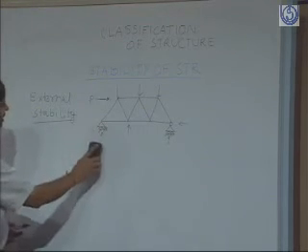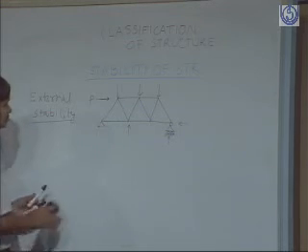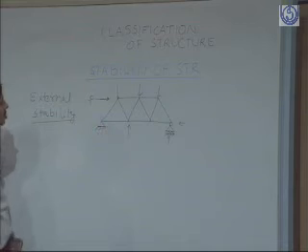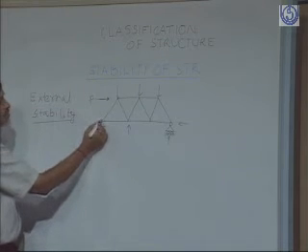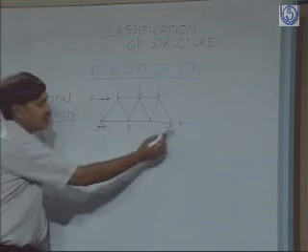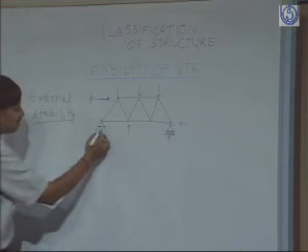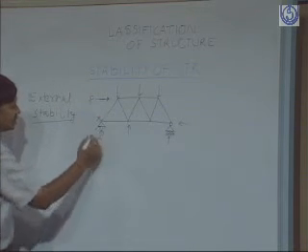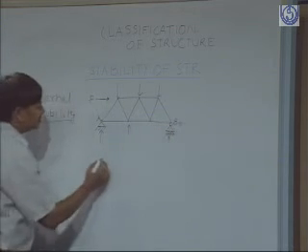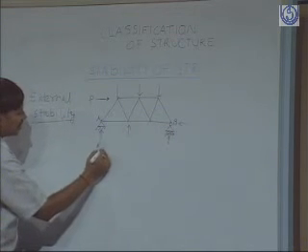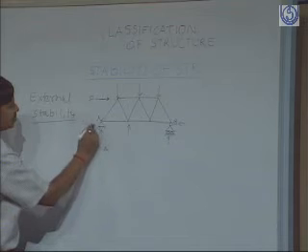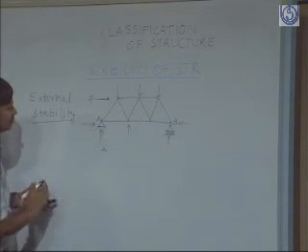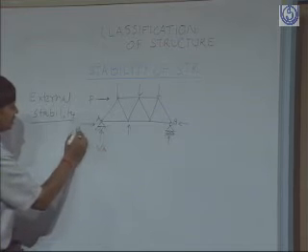So it is necessary to restrain it in x direction also. So suppose we have made it a pin jointed support. So now it is not a roller support, it is only a pin jointed support, and this is a roller support. So here two reactions will be there. One will be in the vertical direction, say RA, and the other will be in the horizontal direction. Let us call them VA and HA.